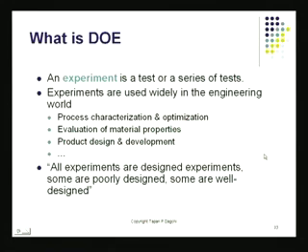In particular, I'm going to be focusing today on the calculation procedures that are involved in DOE. When you conduct DOE, you collect data in a controlled manner. Now, what do you do with the data? Our goal is to understand what the different effects of the different factors are that are impacting the system. We'd also like to know, is that effect significant when we compare it to noise? And also whether there is interaction between the effects of two or three factors that might be affecting this.